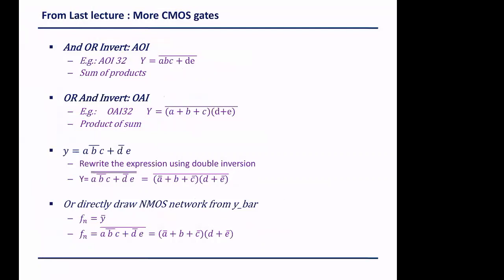Okay, so this is a continuation to what we are looking at, and in this continuation we are now talking about possible types of logic. When I have a library for my design, I will tell you, for example, I have inverter, NAND, NOR, and I will have some generic gates, maybe XOR, and I will have some generic gates for special purpose calculation that will simplify, instead of me using NAND followed by OR as we did before, use more compact structures.